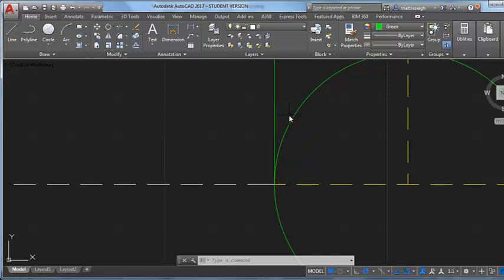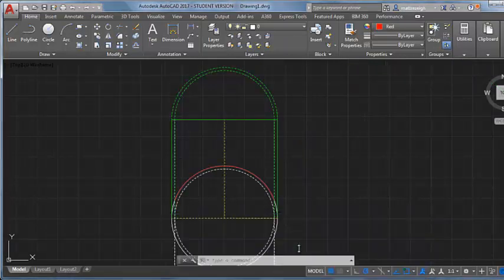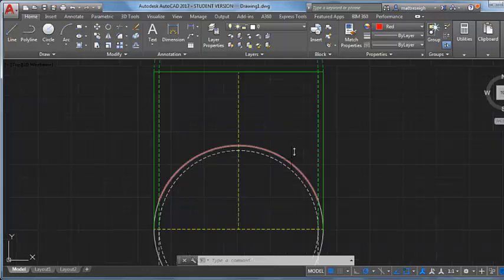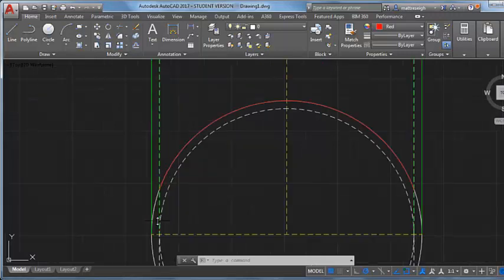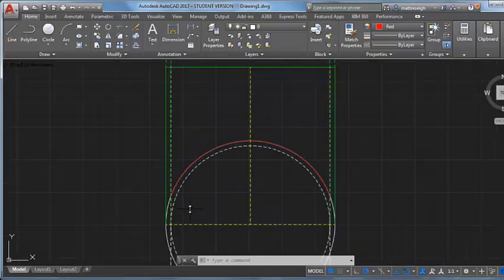So when I'm doing those branch tests, I can bounce over here and show you. This is one that I drew. It's like 12 by 12, and I was aware of the ID dimensions here. When I do those branch tests, I'm really only taking that branch, and this is where the branch is going to sit down on the header, and where that ID is going to hit that header is right there. So you see, I stop that development way before it comes down to center line, way up in here, and that makes it an easier fit up. That becomes more obvious once I've done stuff that's big, heavy, thick wall. I don't take out all that meat that I don't need to. I don't do any unnecessary cutting. That's what those branch developments are, because this would happen if I sat that branch down on there, this ID.